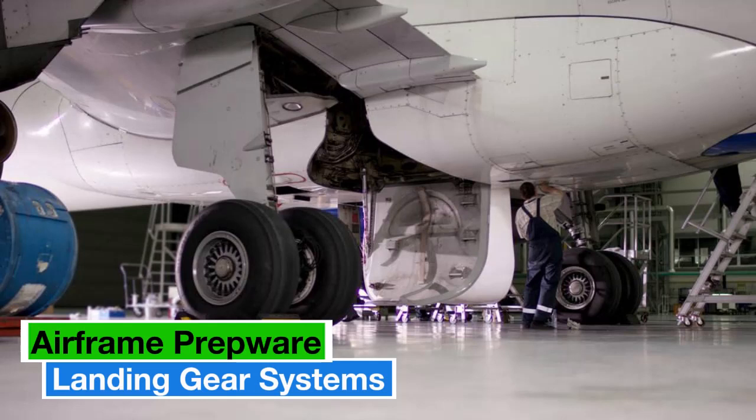The correct inflation pressure for an aircraft tire should be obtained from the Aircraft Service Manual. Why do most aircraft tire manufacturers recommend that the tubes in newly installed tires be first inflated, fully deflated, and then reinflated to the correct pressure? To allow the tube to position itself correctly inside the tire.